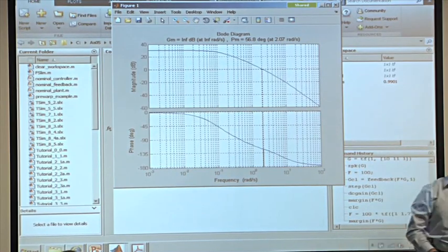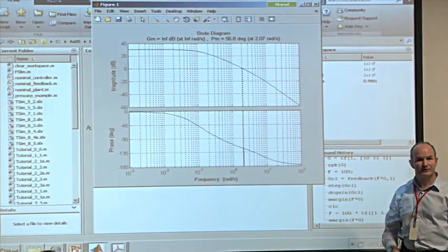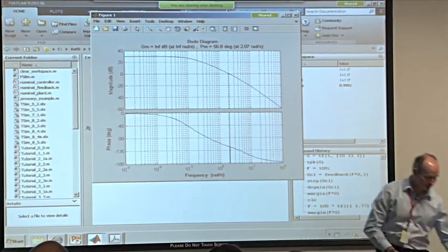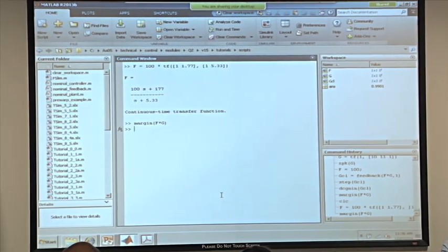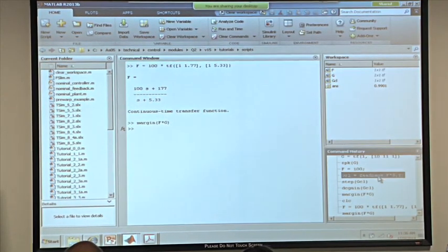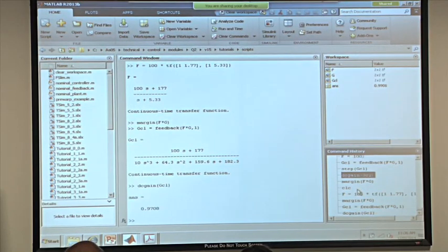Yeah, we've gotten the amplitude change. We've got a 1 over alpha in that transfer function, and it's brought the gain curve down, so it's reduced the crossover frequency, the gain crossover frequency. Even worse than that, if we look at the closed loop transfer function, I'll just highlight the ones I want. There's the closed loop transfer function, and we look at its gain. It's now 3%. So that gain has now violated the steady state error. We need to put that gain back in.